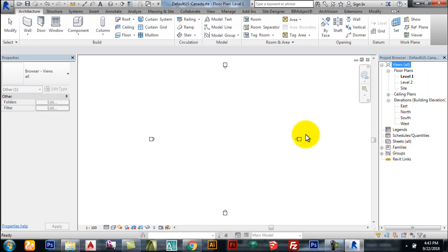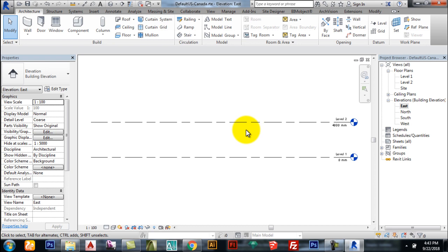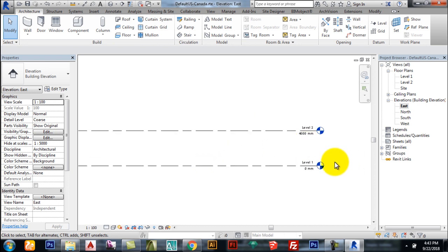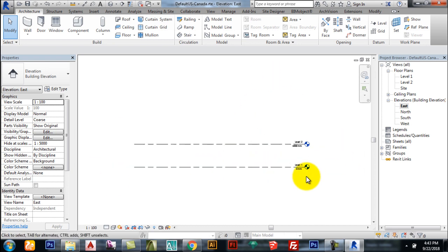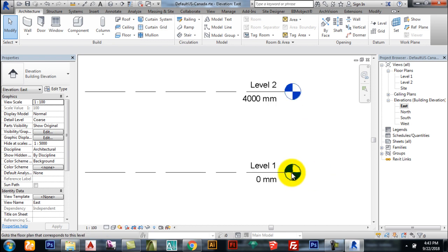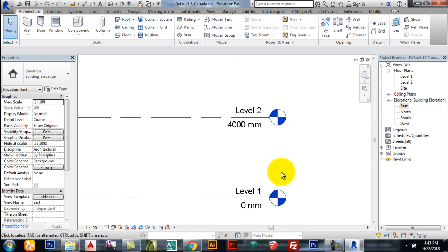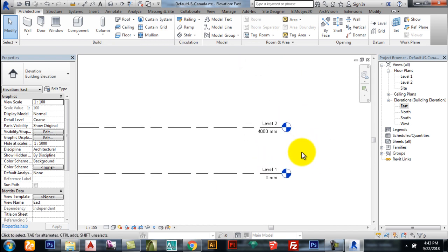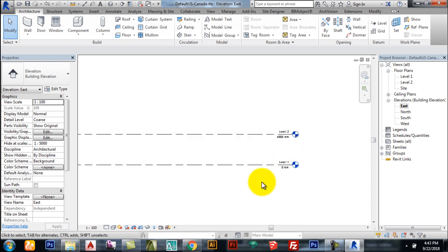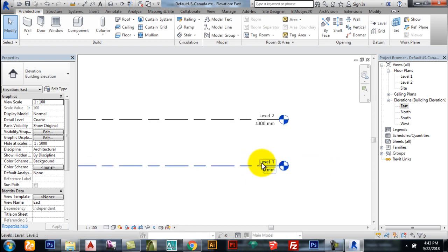So what I'm going to start with now is levels. So we are going to create levels, and we are going to create them from the elevations. Creating levels means you are creating your headroom for your design, for your building. So this is what you will see at first. So you are now going to think about what levels I'm going to include in my drawing.